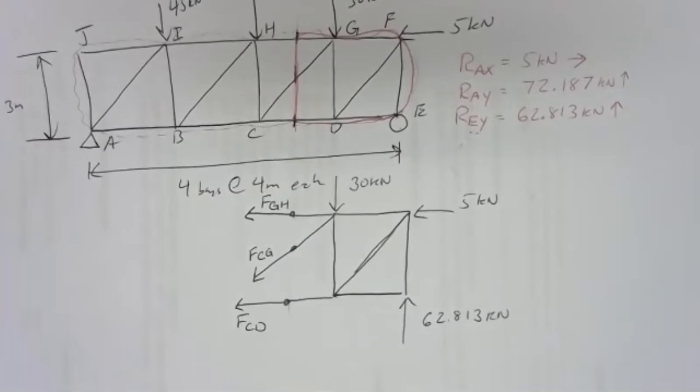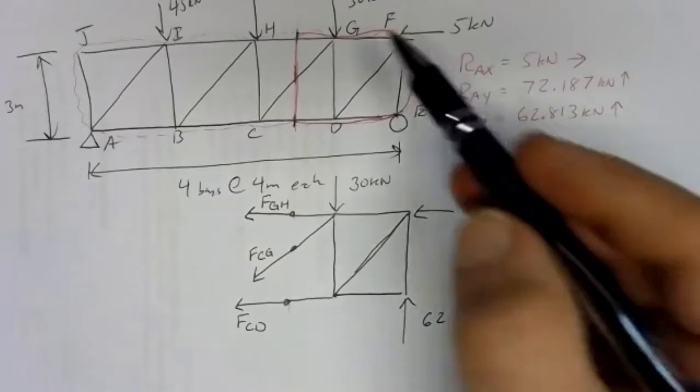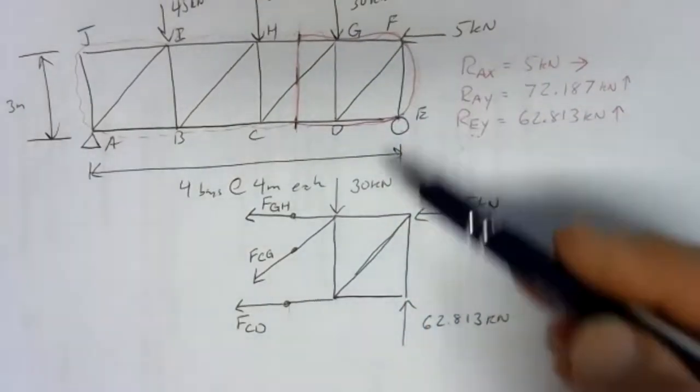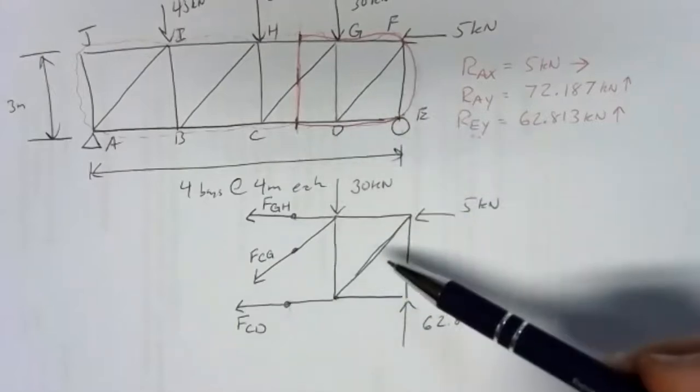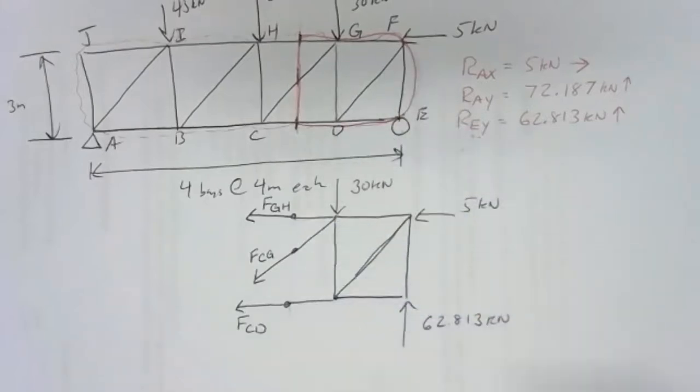So there's our free body diagram of the section of the truss inside that system boundary. Always worth a check to just make sure you've caught everything. Compare your picture to where you've drawn your section, make sure you've got everything cut through and that the external forces are there. A moment of extra care there can save you a lot of time and pain later on.